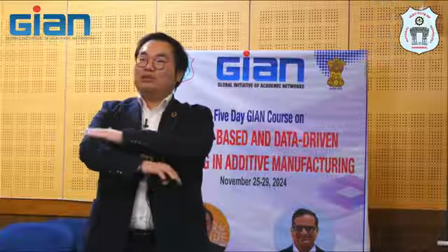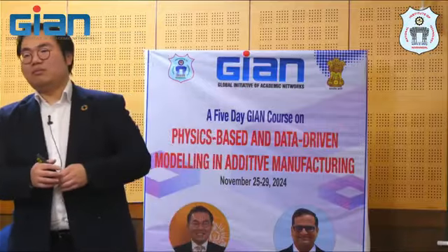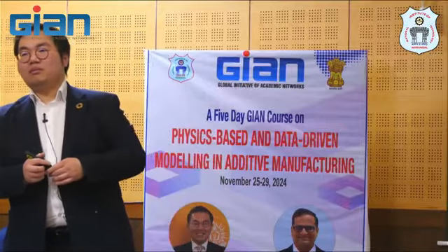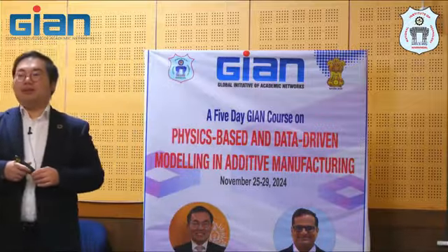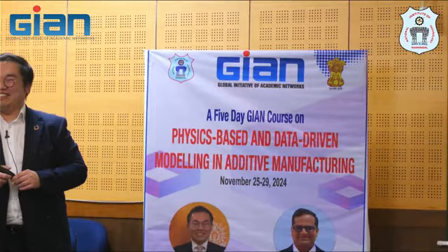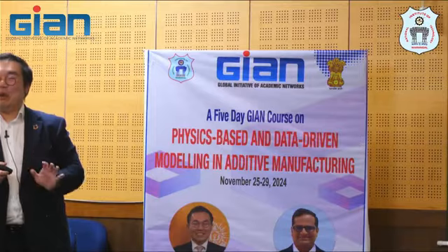And that's why in the new alloy system, this segregation is actually not concentrated, but uniform, what we call solid solution, right? It's solid solution in the material. So that's why there is no preferred segregation in the as-printed soft condition. There is no preferred segregation, or there is no segregation? Everything is there in the solid solution. I would say minimum, just for the sake of science here. Possibility is low.